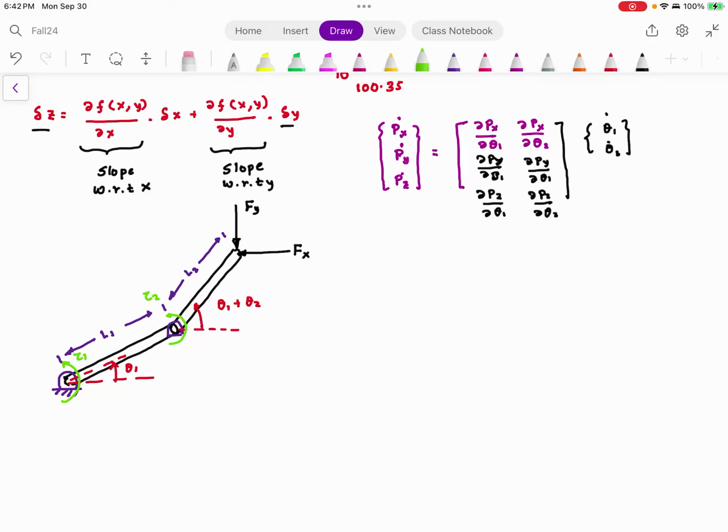Understand, on the end effector, you have forces. If you draw vertical arrows and horizontal arrows, those are forces. We don't have any force acting here, or here. What we have is the torque at the joint. So the question here is, how much torque, which is force times the radius, this is a motor.